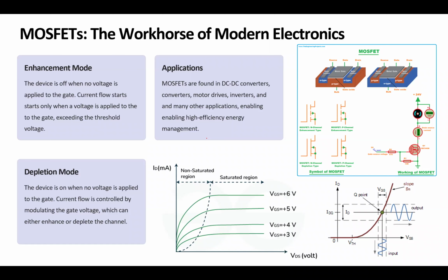Is that clear? Two things are important in these characteristics. One is that after this threshold, you can turn on; before that, you can turn off the MOSFET. So when you apply this threshold voltage to the gate, you basically turn on the MOSFET. This is one control to have in a MOSFET. The second control is that the characteristic of the current to the gate voltage is semi-linear.